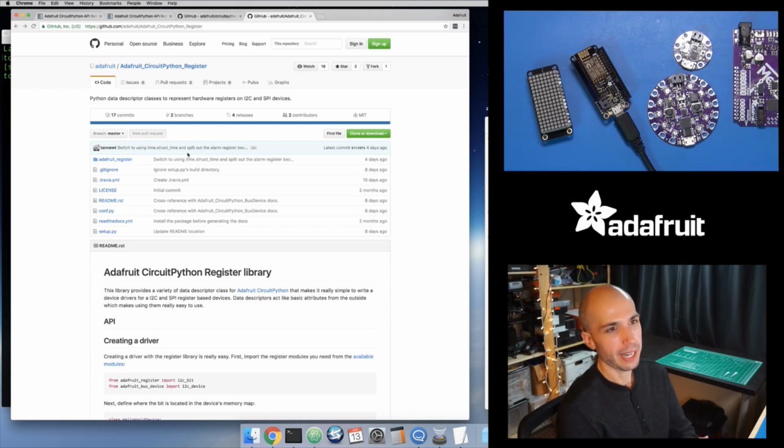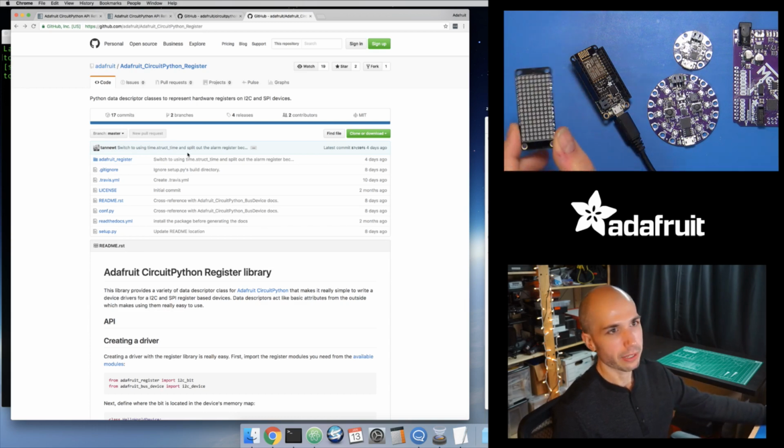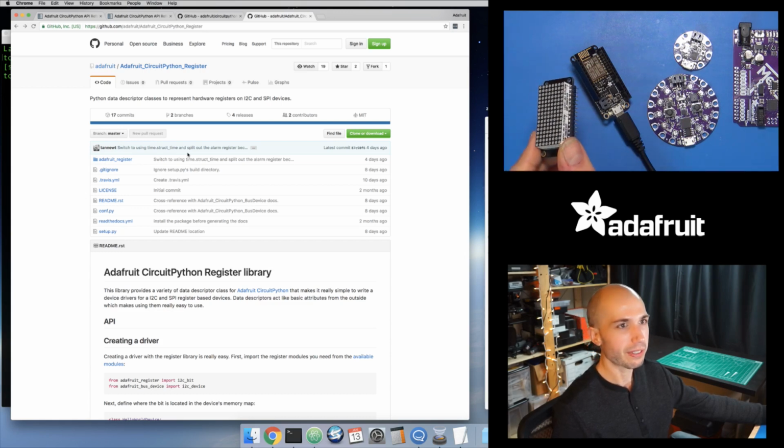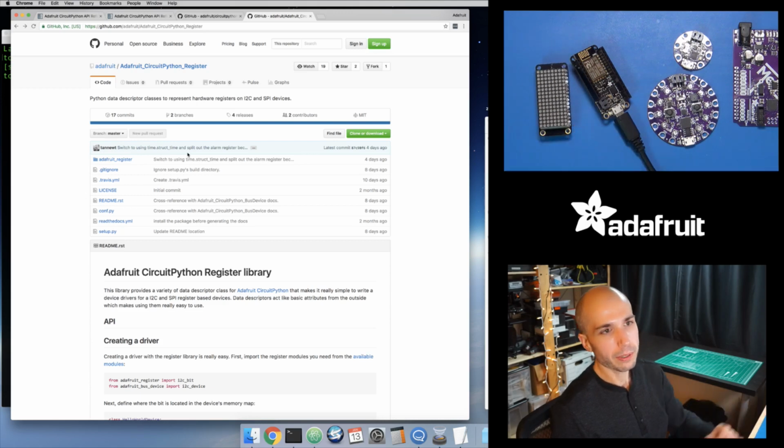So we're basically looking at, because all of these devices, like this little HT chip, it just has a bunch of registers. So there's a register that controls which LEDs are turned on and which ones are turned off, and if it's blinking, or what's the intensity of the light, and things like that. And so we've taken some higher level abstractions to look at how we can simplify the drivers and just operate on those registers at a register level.